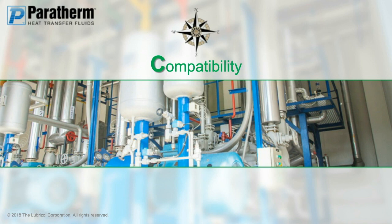But it's also really important, even though you drained the entire system out, to make sure that what you have left in the system is going to be at a percentage that's not going to cause problems. And the rule of thumb that we typically see is around 15% of the fluid, just due to the inherent nature of most systems, will be left in that system at the low points. It's virtually impossible to drain, just a straight gravity drain, that system and get all the fluid out.